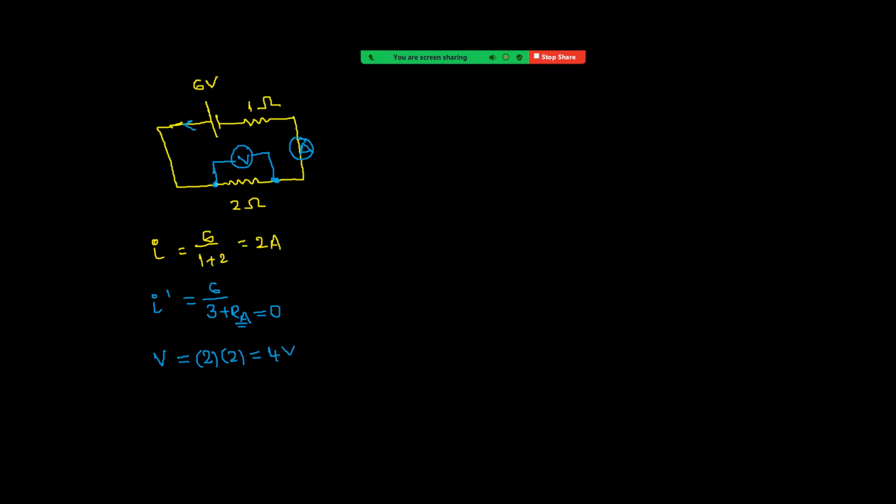The reason is that for its working, means for deflection, it requires current. So some current flow must be there in this for its working. That's why reading given by the voltmeter will be less than the actual value. Okay. So what we are saying is for ideal voltmeter, resistance is infinity. And how to connect, means we have to connect parallel to the circuit.